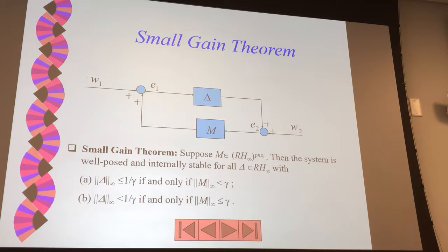Because if you do a series expansion, you know that the feedback signal contains many frequencies, and at certain frequencies, the phase actually passes 180 degrees. Then you reverse the negative, negative, and it becomes positive. Okay? So when people ask, is positive feedback bad? You should say, no, not really. Sometimes it's useful.